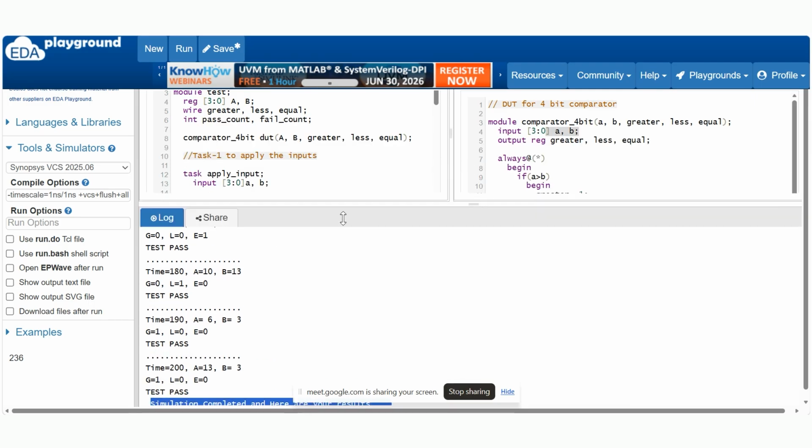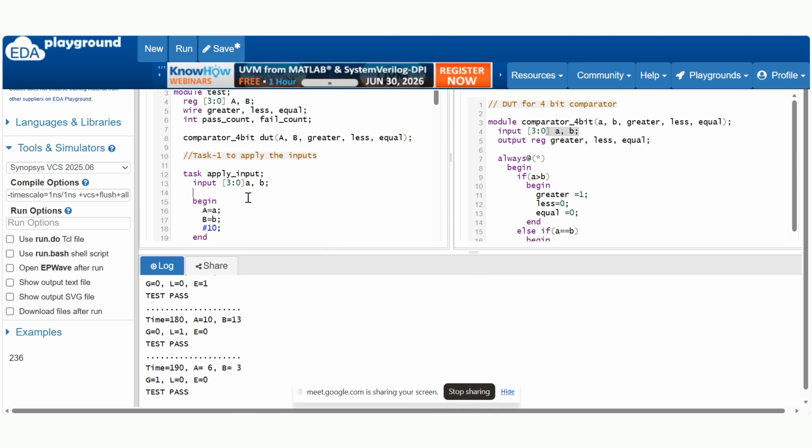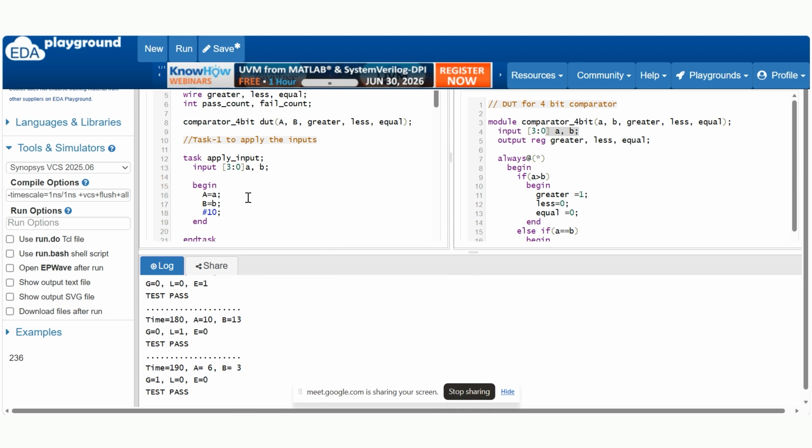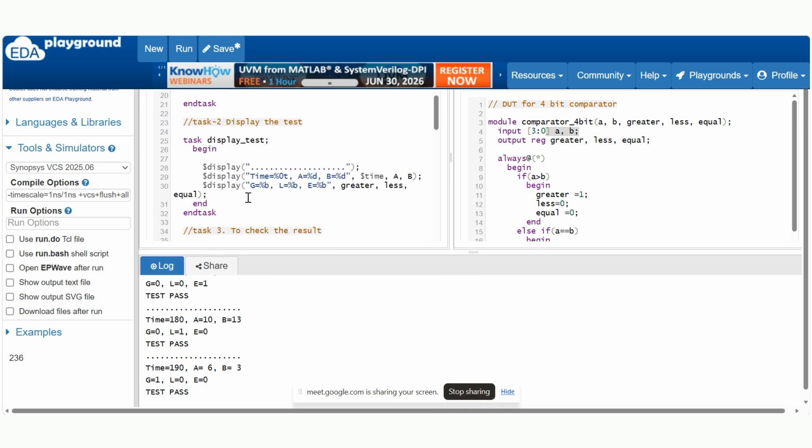So nowadays in the industry, people are developing such VIPs which do the verification on an automated basis and give the summary at the end. And every time the engineers will try to make it bug free, either DUT bug or verification bug. Once it is completely bug free and you are getting coverage of more than 90%, 100%, then it will be sent to sign off from the front end, and it will be sent to the PD.